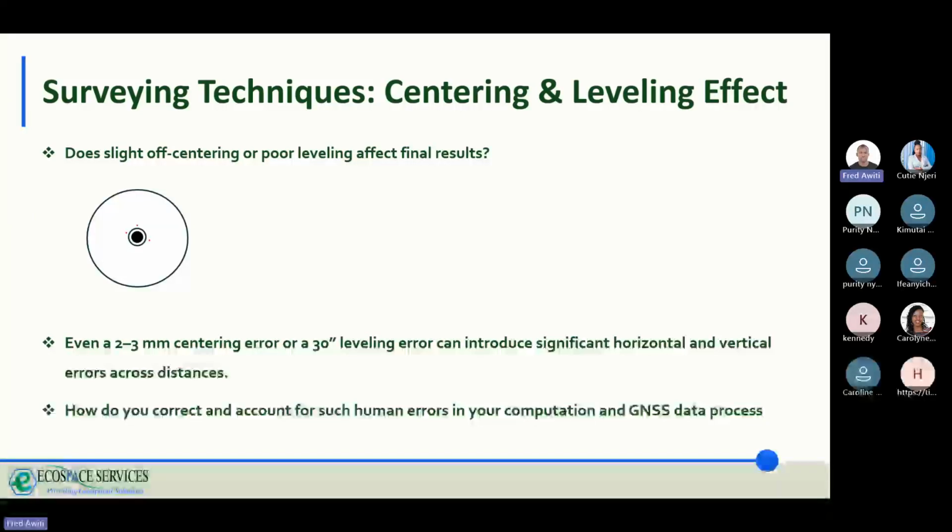So with the current technology, it is not as before where you just process your data, submit it to whoever wants it, and then that is it. There are what we call the lasers to be able to determine if a building is straight. When you go to a construction site, the fundis will tell you they're using a kabir. But nowadays, there are laser distance measurements that can determine if a building is straight. And that's why I was saying we need to look at what we call the 3D analysis in surveying, in sectional properties. Why do you need a laser scanner to do your sectional properties?